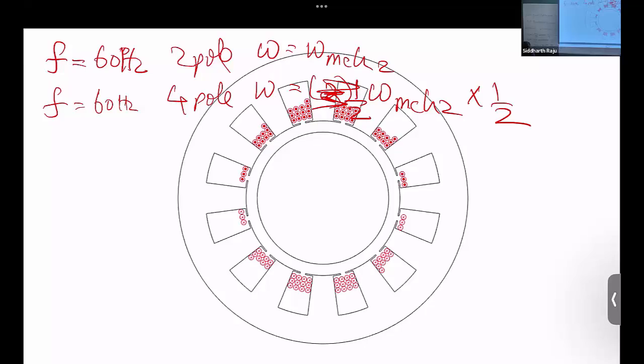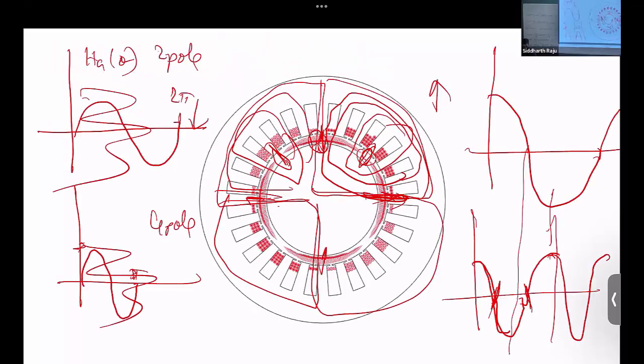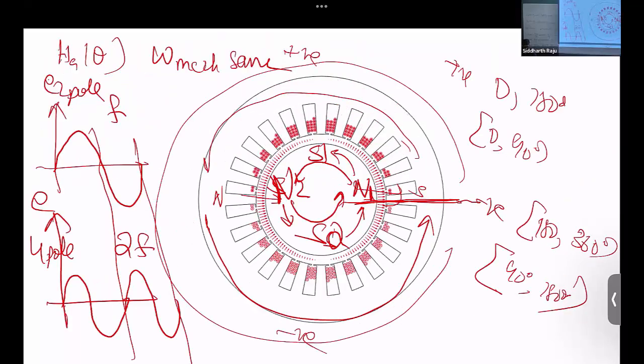Whenever you have that kind of mismatch, go back to Fourier. If you look at our magnetic field in the air gap, go back to a simple case of a two-pole: we have a sinusoidally created magnetic field in the air gap, and then the rotor is going to create its own sinusoidal magnetic field, which we'll get to later. The product of these two interacts to create the torque that we saw, right? Taking the product of the two magnetic fields and integrating it over the whole volume would give me the total energy and the torque associated with it, and so on.